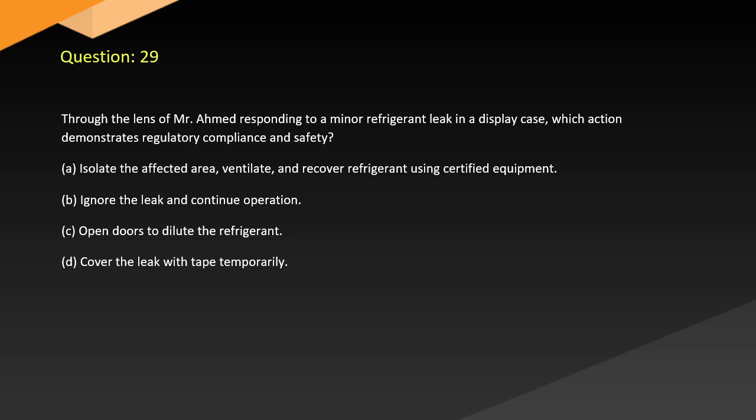Question 29. Through the lens of ISTA, Ahmed is responding to a minor refrigerant leak in a display case. Which action demonstrates regulatory compliance and safety? A. Isolate the affected area, ventilate, and recover refrigerant using certified equipment. B. Ignore the leak and continue operation. C. Open doors to dilute the refrigerant. D. Cover the leak with tape temporarily.